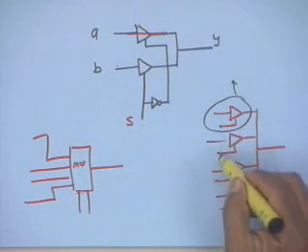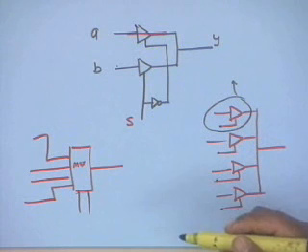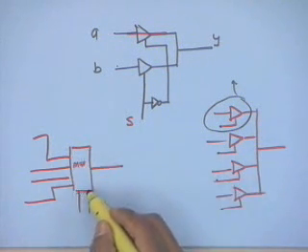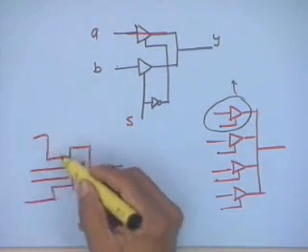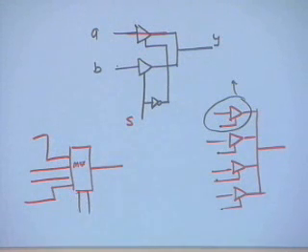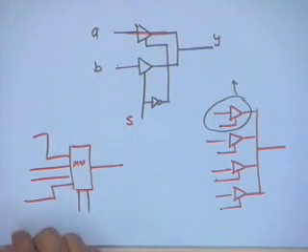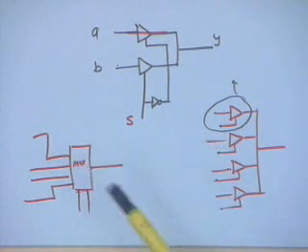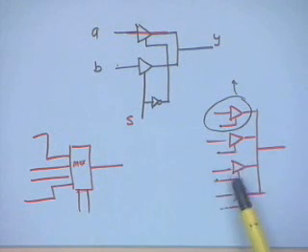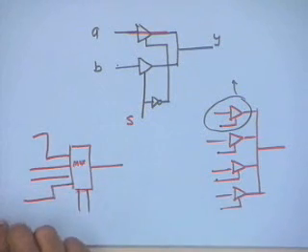Of course, we do have to ensure that they are mutually exclusive, and that is logically ensured by giving different addresses. Whereas if one has to implement using a multiplexer, you actually need to have physical wires drawn from there, and there is nothing that you can remove in this manner. So that is a very fundamental advantage of using tri-state buffers over something like multiplexers, because in a sense this also implements multiplexing logic, but it provides you a certain flexibility in terms of presence or absence of components.